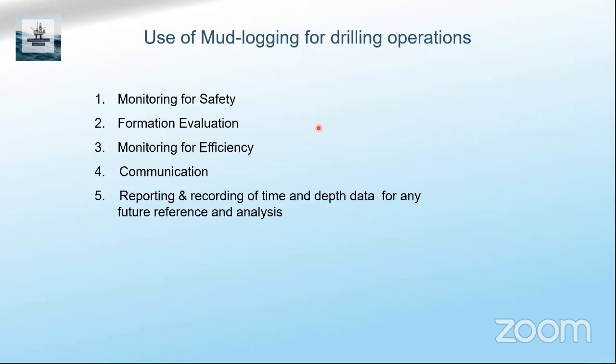And also the rig floor, the driller, he is not able to watch his gauges all the time. He is very busy physically, handling the drilling, the mechanical stuff and so on. So then who is there? He may not know about the pits, a lot of drilling fluid transfer, the gains, and sometimes losses. But it is the mudlogging crew who are there inside their cabin with all the sophisticated charts and so on, the drilling parameters, the alarm setting.